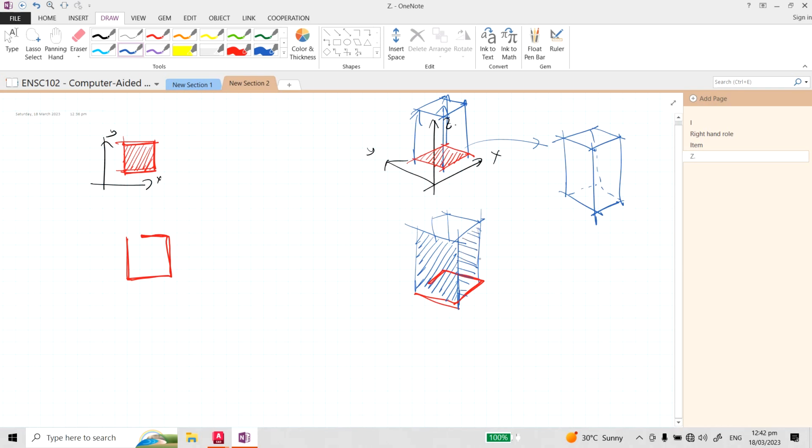So if our intention is to make it a solid, make sure that all the lines right here are closed together, and not just close together, but rather made as one single polyline.